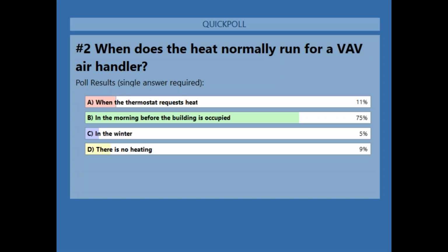Now, we could build it that way, and we do. So, for example, obviously we do Carrier equipment at TEC here. We have Carrier VAV rooftop units that have the ability to do tempering, and we have other ones that don't have the ability to do tempering. You could buy it either way. The ones that have tempering are the ones where we have an accessory called staged gas heat, or sometimes referred to as modulating gas heat. And those will have stainless steel burners in them, so we can have the ability to throttle the gas heat back without having to worry about condensation and corrosion on that guy.